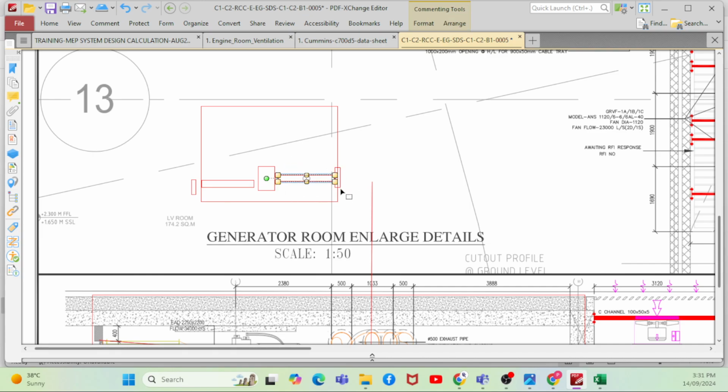My pressure drop is exceeding 126 Pascal, and when I calculate this pressure drop, it is more than 126 Pascal. So in this case, I require an intake fan to take care of this pressure drop and a discharge fan to take care of this pressure drop. So this is the case, yeah, I go with both external fans.